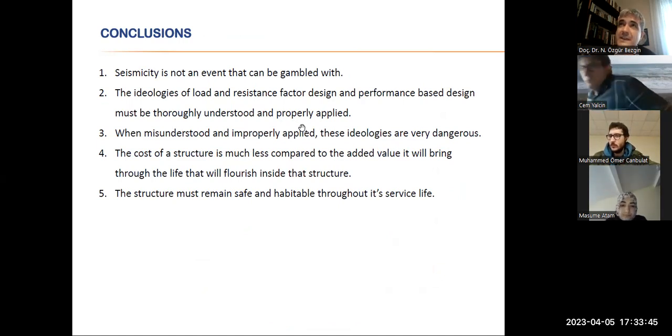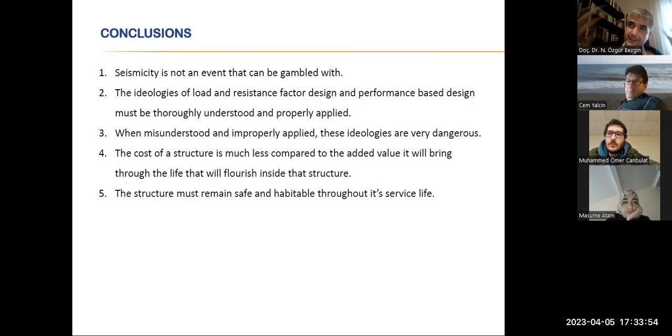Because sometimes when we say energy absorption, right? This is a very clean word, two words, energy absorption. Well, if you have an explicit response to that, like a damper, a friction pendulum, energy absorber, whatever, then fine. But if you are just constructing your reinforced concrete and you are talking about energy absorption, you are talking about concrete cracking. You are talking about destruction. Energy absorption, you know, it is a very sweet word, like I absorbed energy. How do you absorb the energy? By cracking. That's how you absorb the energy. Your building will not look the same after it absorbs that energy.